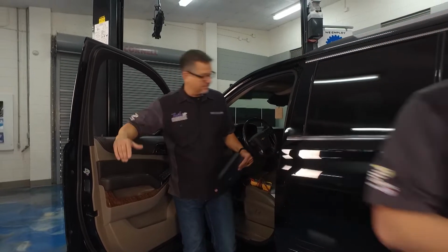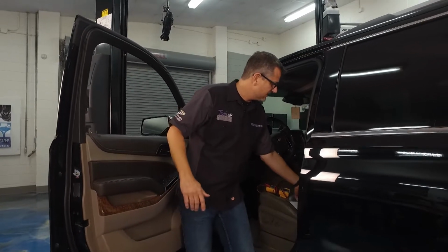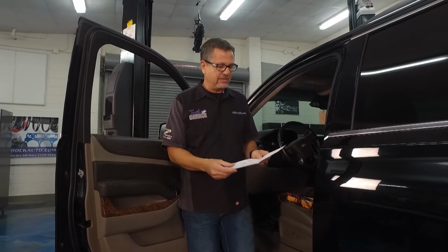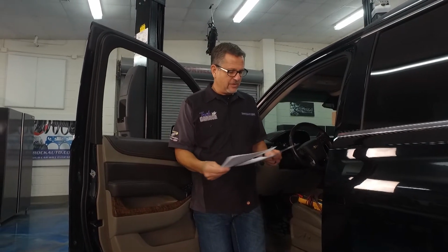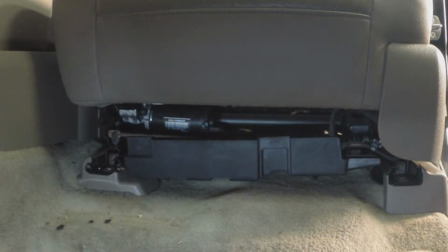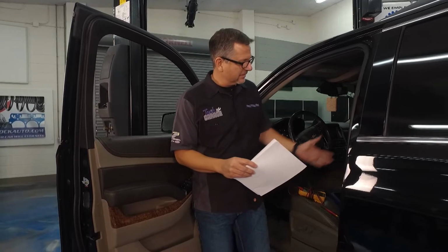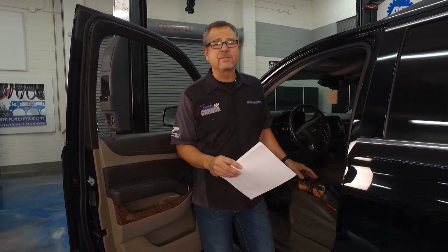Well, that makes all the sense in the world what Dave was talking about, because the seat's not vibrating. I believe it used to. So I got all the information. That's the first thing you have to do. The flow chart, all that. It showed that the actual module is located underneath the seat. So what I'm going to have to do is unbolt the seat, get it up, and contort it a little bit so we can gain access to that module and make some tests.